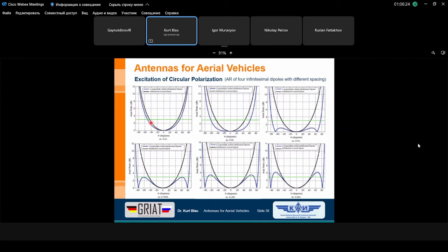And so we can say that if the distance of the two dipole pairs is 0.2 lambda, then we have about plus minus 50 degree as a threshold, or totally 100 degree opening angle. I cannot say here half power beamwidth, because it's not true.